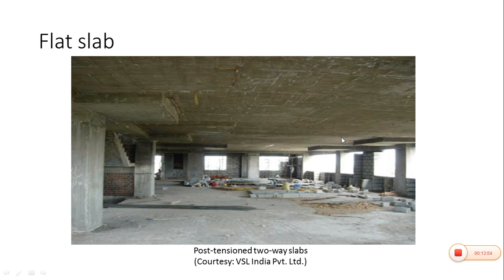Here we have the flat slab. In a flat slab, as we discussed, there are no beams, but near the column, at the top of the column, we have a projected portion over here. We can see this projected portion in this photograph.